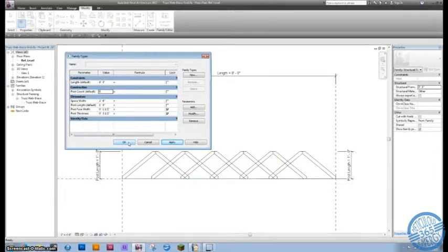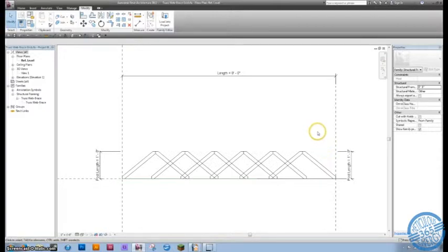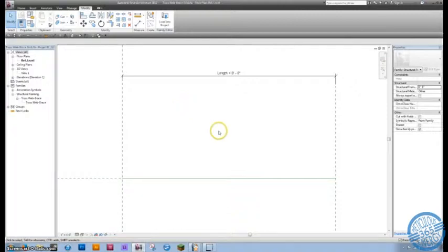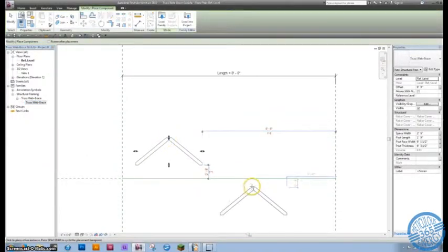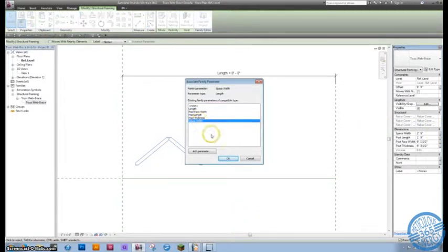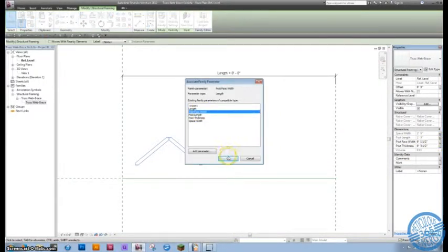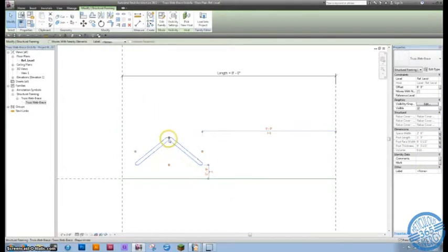But let's look at how to build this. So I'm just going to take these and delete them, and we will do this from scratch. So step 1, place your element. Step 2, link all your parameters together, because we don't want to miss this step. We will link together the space width, the post length, post faced width, and post thickness. Okay, so our arrows have turned into dots because it is being controlled via a parameter.